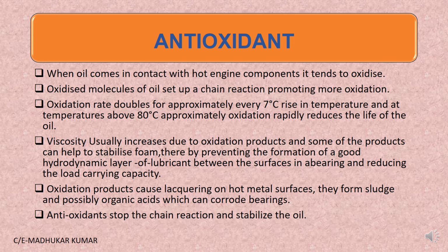So we have to have the antioxidant additives, which prevent the oxidation products, and antioxidants stop this chain reaction and stabilize the oil. Basically, these oxidation products also cause lacquering on hot metal surfaces when they form sludge, and possibly organic acids which can corrode the bearing. So acid formation is also there, and corrosion of the components will also happen. So antioxidants stop this completely, the chain reaction is stopped, and the oil is stabilized and protected.